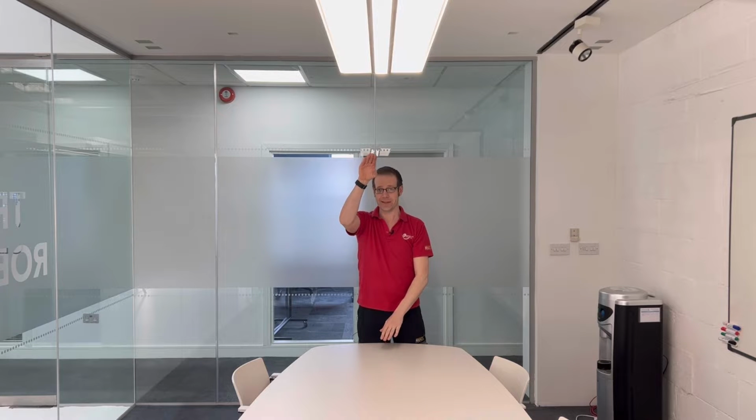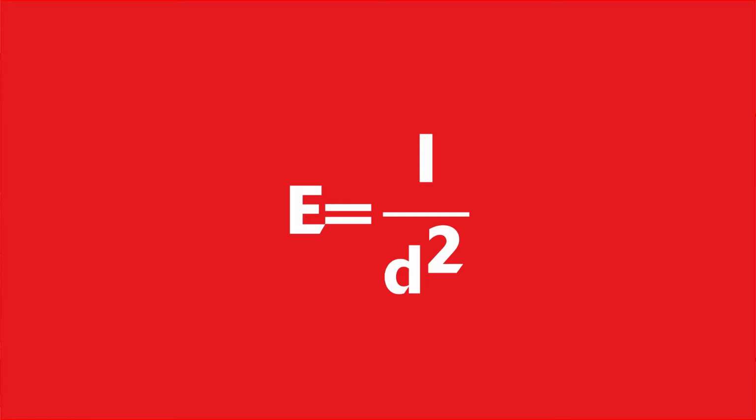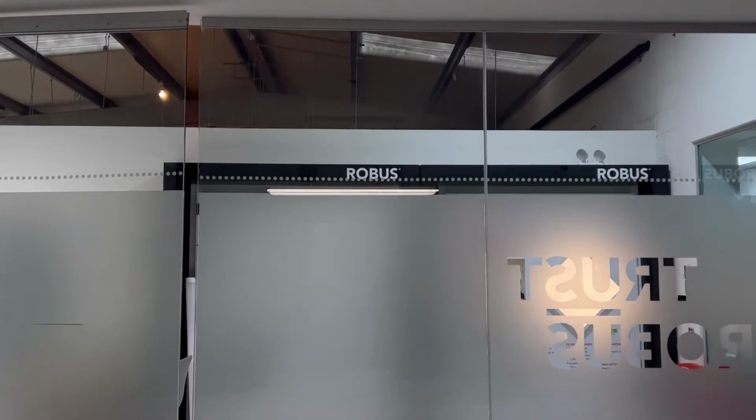Now, when light leaves a fitting, there's a number of different things that affect how much of that light actually reaches the surface that it's illuminating, and the biggest culprit is distance. Light behaves according to something called the inverse square law, which is a type of calculation found all over the place in physics, and we'll explain this in a bit more detail in a minute. But for now, it's enough to know that the further a light source is from the surface that it's illuminating, the lower the light level will be at that point.